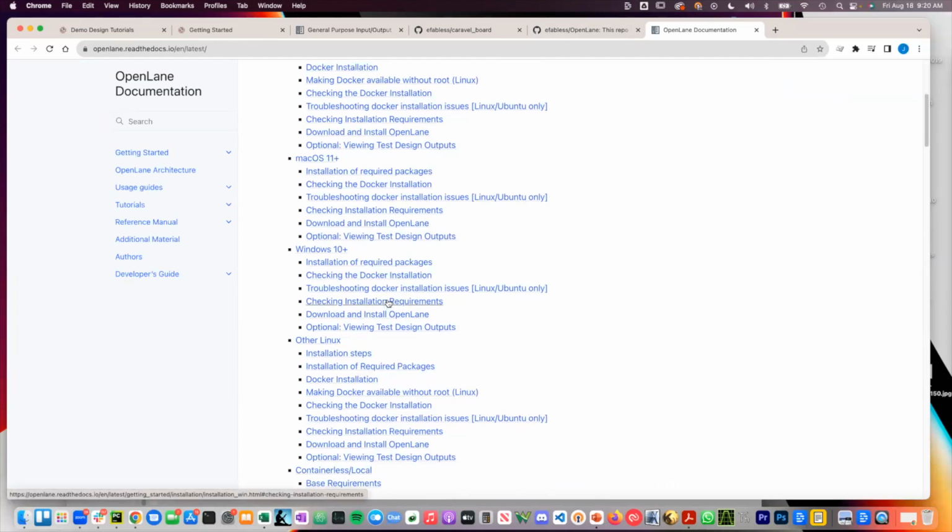So to address the question tactically, the answer is yes to delay, yes to power, although I believe by default that it's turned off. And I think that the current answer is no to area. I will say that you won't get it for RTL. You've got to go through the synthesis process to get those answers. So you've got to run the flow, go through synthesis to get the delay and the power report. And I think that power is by default turned off. And I don't remember seeing an area report, but you can get gate counts.